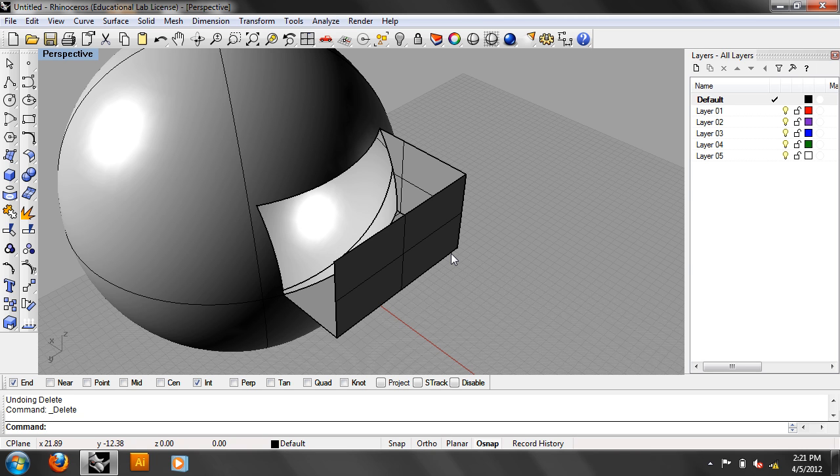It's more complicated. But as you get into more complicated forms, the computer doesn't know what to erase and what not to erase, and it doesn't know what your intention is. And when you get more and more complicated forms, the Boolean algorithm, the kind of automated thing, gets slower and slower, and it crunches. And so it's better to just model it cleanly yourself than to have the Boolean do it for you, right?